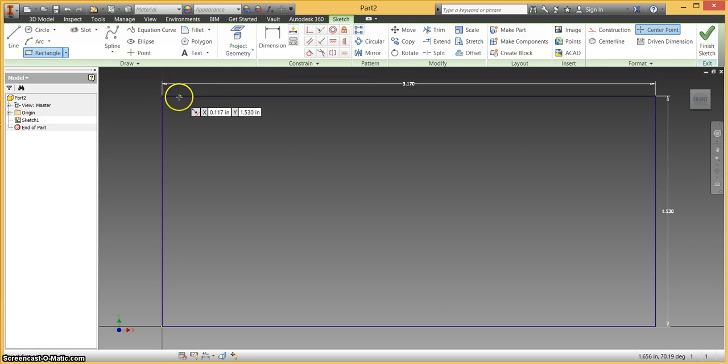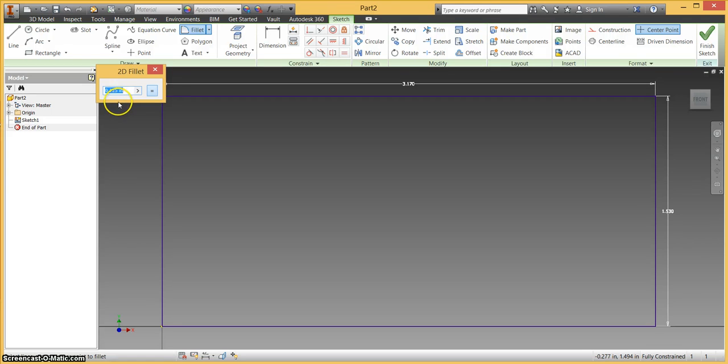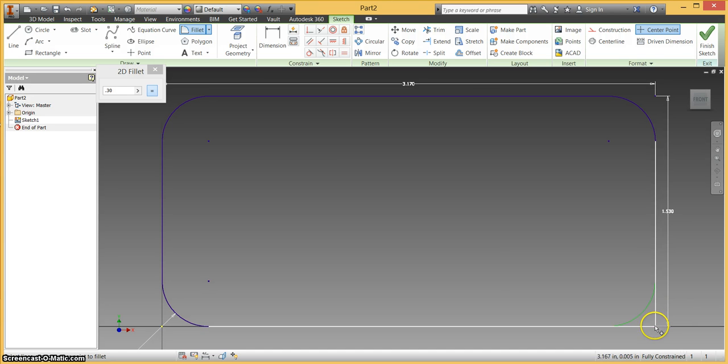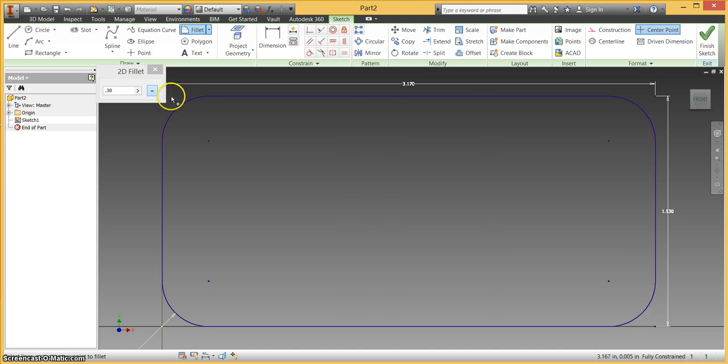Now I want to put some fillets on these edges. We've gone over this in class. Fillets are in my draw tab. The fillets on this front of the car, if you look at the upper left-hand isometric, we can see that at 4 times R.30, that means there's a fillet on each of the 4 corners. I can select the 2 different lines for the corner, or if I get really right up in the corner of that thing, one click will let me get there, although sometimes it takes longer to get to that corner thing than it's worth. Those are the fillets I need.